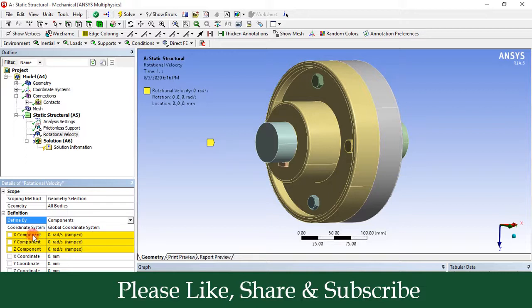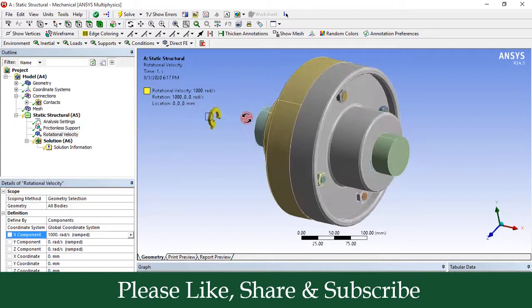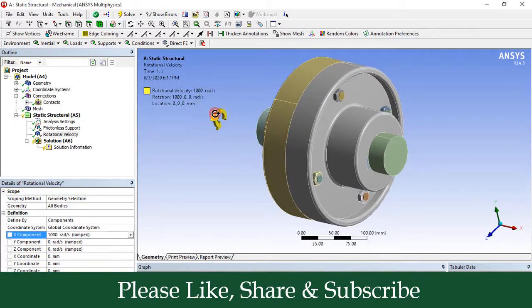Now you have to select the value of x component, y component and z component of rotational velocity. If you look at this model, this shaft axis is along x axis, so we have to enter the value of x component of rotational velocity. So I will enter here 1000 radian per second, and others will be 0. So you can see here, this input shaft will rotate in this direction about x axis, as the shaft axis is along the x axis.